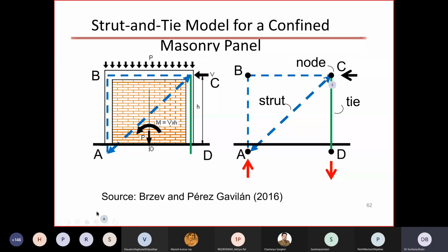What is also important is to note the nodes between these adjacent truss elements. So these are pins. So in confined masonry, we don't have rigid connections. We don't assume that there is any moment transfer between this vertical tie column and horizontal tie beam. That's why these big black dots or circles are shown. So this is also possible, and it's particularly suitable for walls with openings.